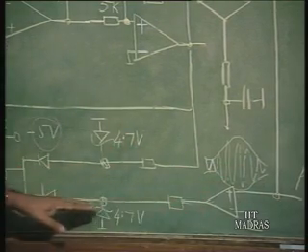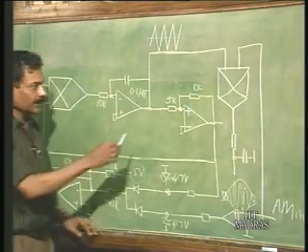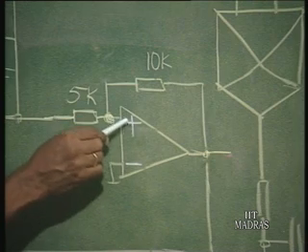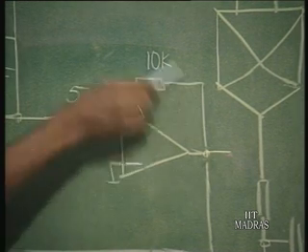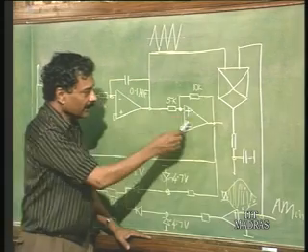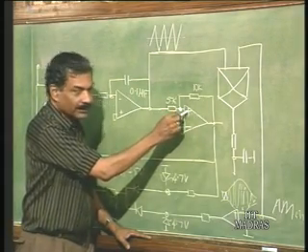So, in this phase lock loop, there is a correction here. In the last diagram we had marked minus plus, but it is plus here and minus here, so that this is a Schmitt trigger, otherwise it will not work. Even though the experimental setup has been connected with plus here and minus here, in the diagram it was marked minus here and plus here.